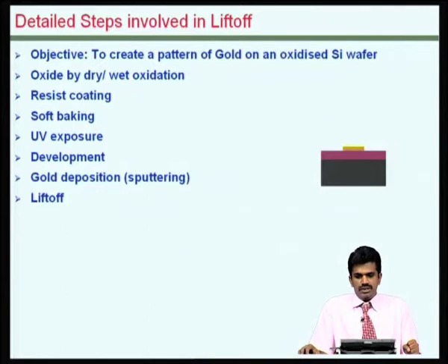But what is critical in this case is to have the step coverage, so that there is no continuity between these gold layers, and possibly a good thickness of the resist can ensure that.